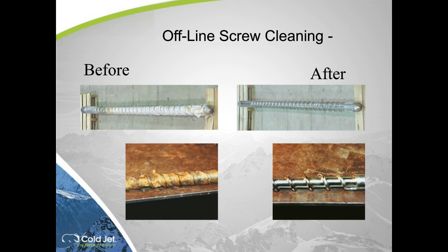For this, the 3 millimeter pellets bring a little bit more kinetic energy to the game. The diameter of the screw does matter. How thick is that plastic, particularly if you let it get cold, as in the example here. And crystallines seem to respond just a little bit better than some of the amorphous resins, but they clean up rather nicely.